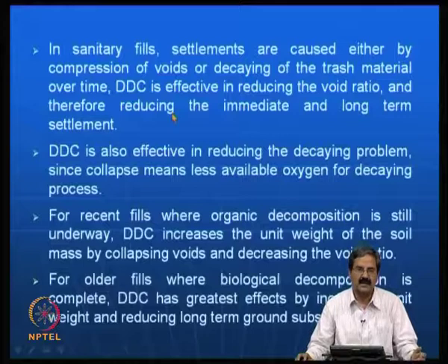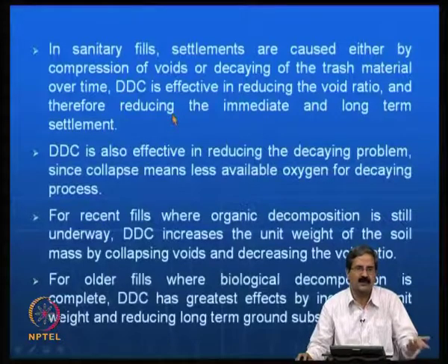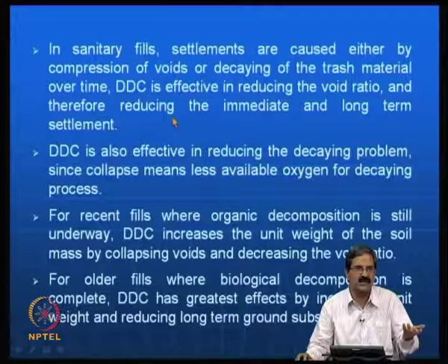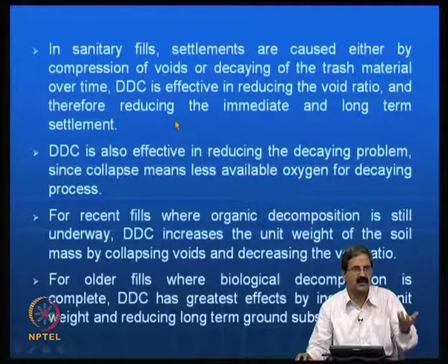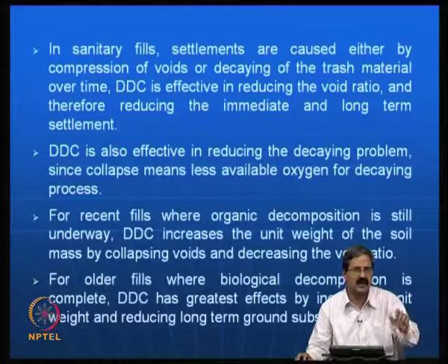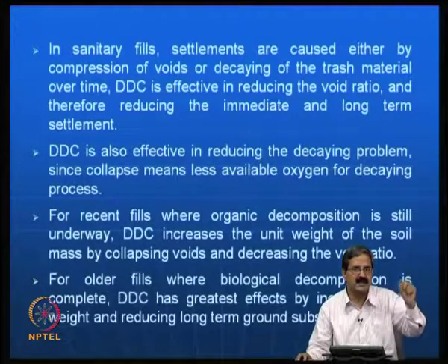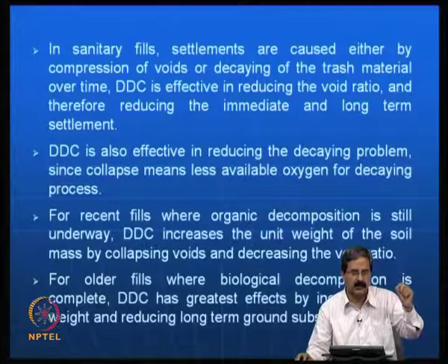I may say some void ratio is there, but what is this void ratio? The definition of void ratio is somewhat tricky when you have biodegradable matter present. You may calculate some void ratio now, but after the biodegradation is complete, the void ratio has two components: the voids present in the non-biodegradable portion and the voids present in the biodegradable portion.